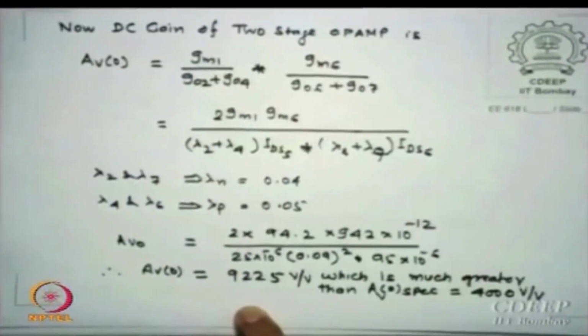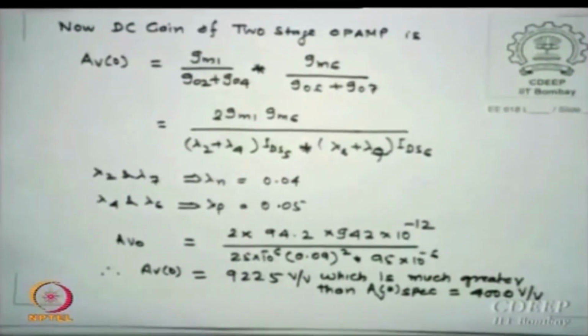Okay, what is the problem if I use a higher value? The bandwidth will go down. Some limit may say I want at least this much bandwidth, then I cannot play with this gain. So I say okay, bring it down a little, then the bandwidth will increase. Because gain bandwidth is given to you, if you reduce the gain the bandwidth will increase. So then take a limit from the bandwidth and recycle this. Okay, this is how OPAMPs are actually designed.